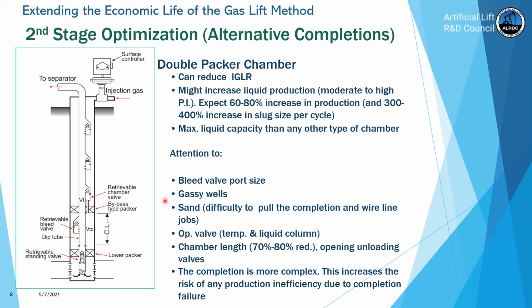Now, also, if the gas-oil ratio is very high, you end up filling the whole thing with liquid that has a very light gradient. That means that there is a lot of gas still in solution, and the net volume of liquid is not what you expect. It's actually much less than that.